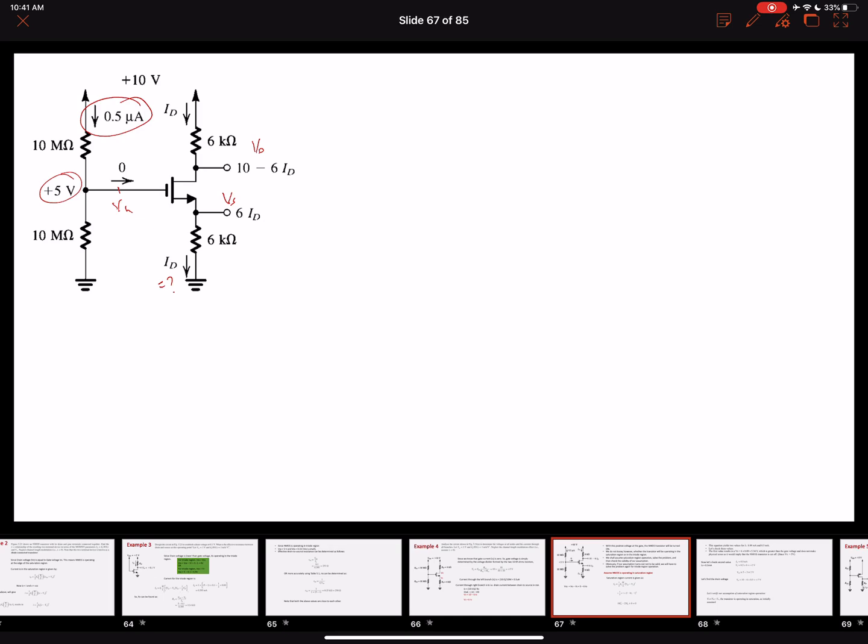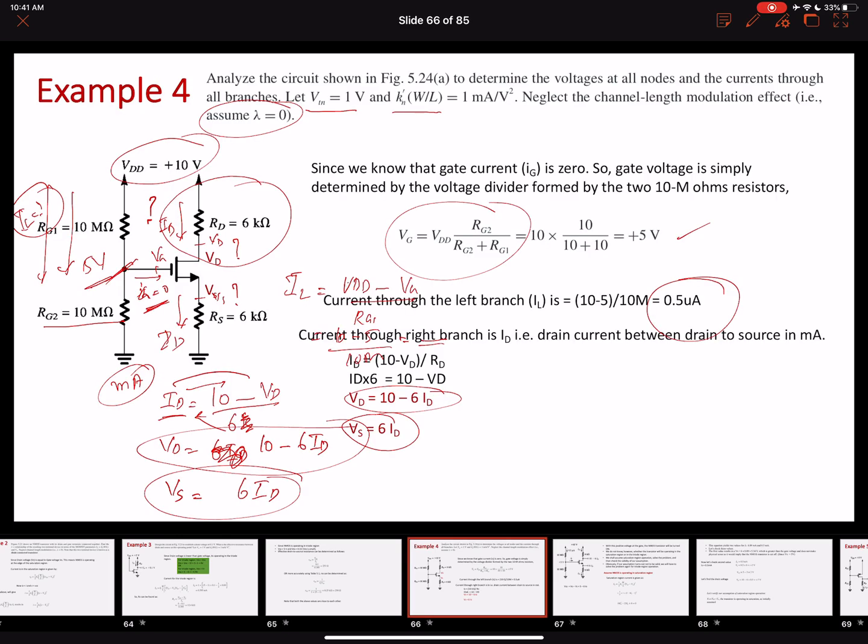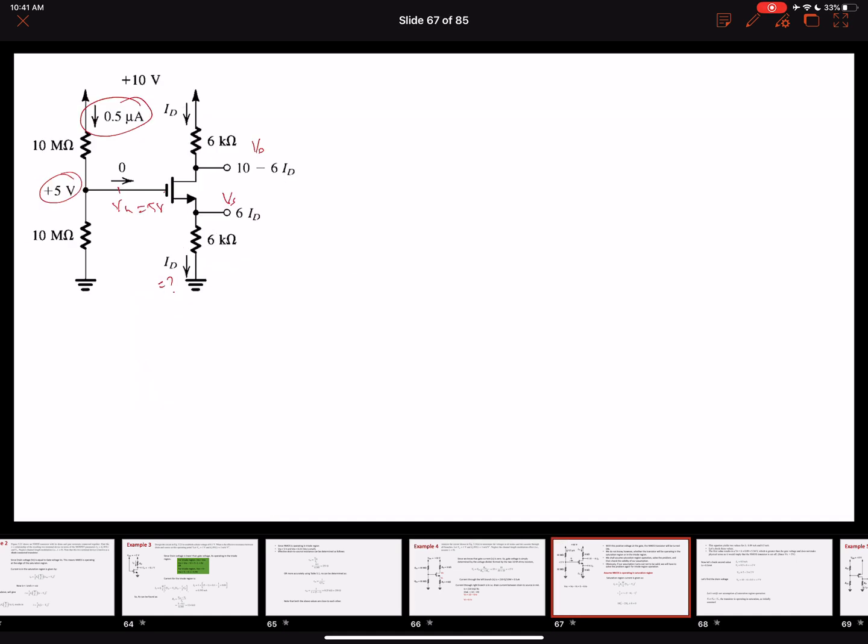In order to do that, we can always start with finding the drain current value. To find the drain current, we need to first figure out in which region our transistor is operating. Let's look at the voltage values here. At the gate terminal, we are applying 5 volts to this NMOS transistor, and the threshold voltage is 1 volt. So this means that the transistor will be turned on by this 5 volts. We haven't determined the value of the source voltage, so we're going to do that.